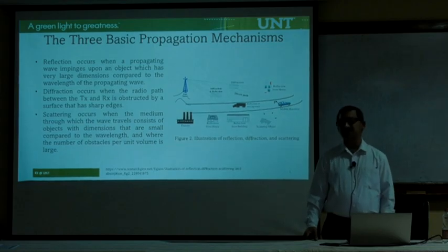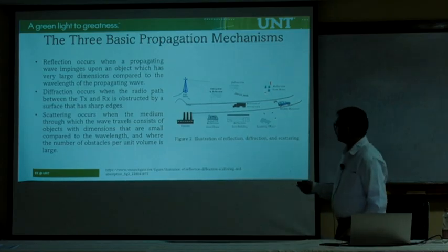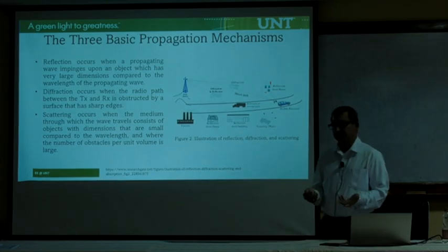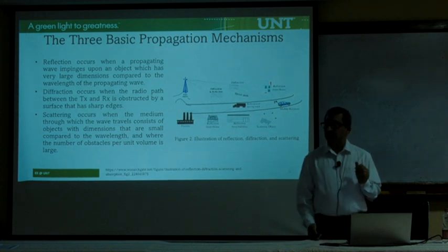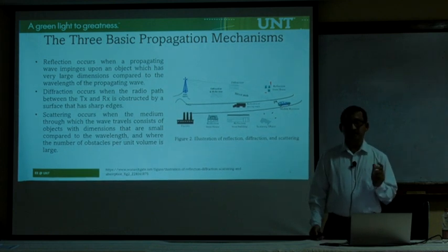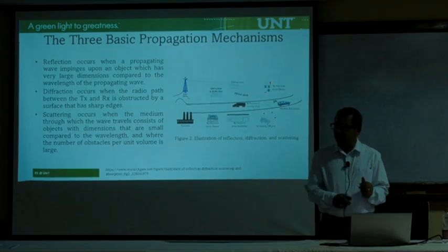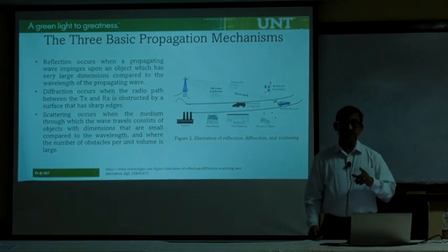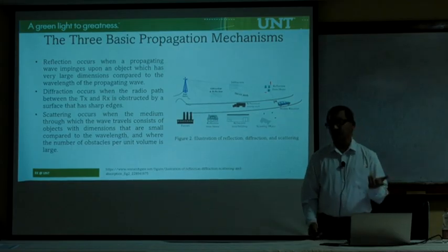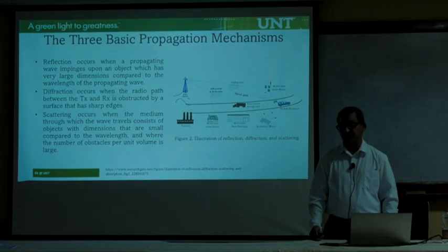Okay? And there is one more thing you have to think about, the distance. If the path takes longer time, the distance is longer, then you can assume that the power loss is larger, right? But compared to the speed of light, 400 feet or even 1 kilometer is not really a big deal. But the problem is, the path loss is proportional to d squared. So that's where you encounter loss. So that is how the distance d plays a role.